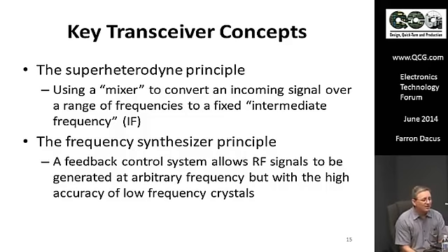Now, the reason this thing works so great that it's lasted 100 years and no end in sight is because of what I mentioned earlier. There's a lot of dynamic range in radio communications systems. So you're generally looking to get right down to the noise floor. And getting down to the noise floor means you need excellent filtering. So if you've got, say, a voice signal consuming 10 kilohertz of bandwidth, you want to put surgical filtering around that signal and not introduce other noise, because noise is proportional to bandwidth.